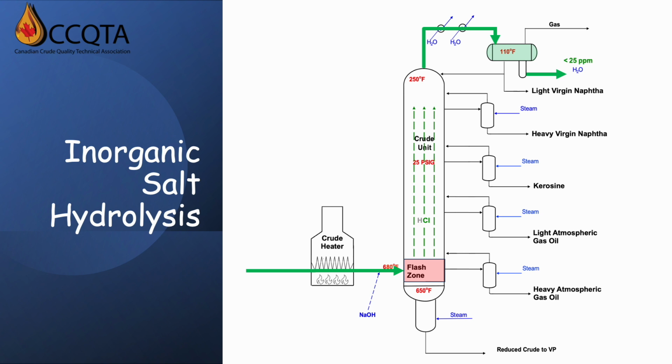Initial dew point pHs of the condensed water phase can often drop below 4.5 and lead to corrosion of overhead equipment. Historically, ammonia has been injected into the tower overhead to help neutralize the acid. However, since ammonium chloride forms fouling or corrosive deposits, most crude units now employ proprietary non-fouling neutralizers to manage corrosion, and we'll look at those issues a little further later on.